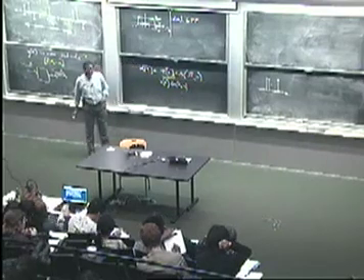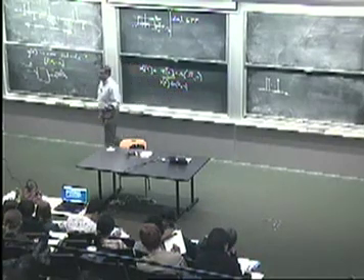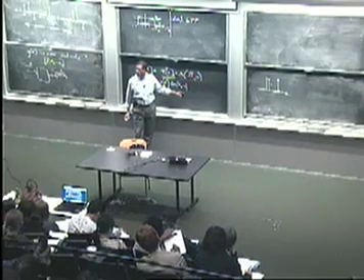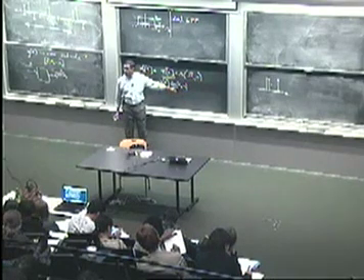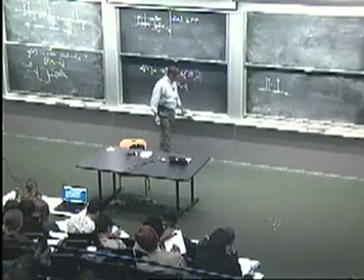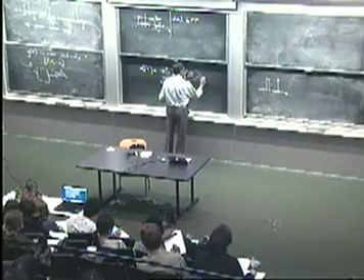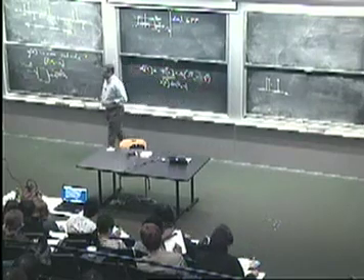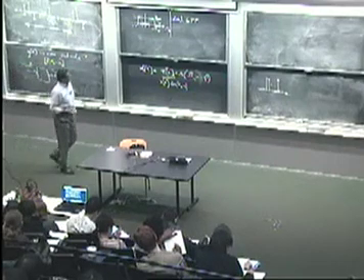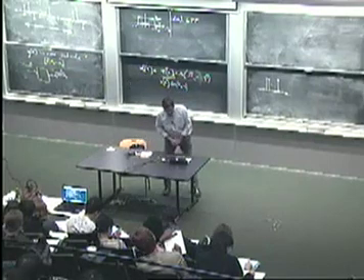But there's a bit of a problem here, which is that even if you've been told what carrier frequency your sender is going to use, you might not know exactly what phase. It's typically the case that you don't know what the phase is on this cosine. So you know omega c, but you don't know exactly the phase, which means that your local oscillator or your local carrier multiplication here will end up having some offset relative to the carrier used at the transmitting end. Okay? And so the question is, if we track this through, what happens through the demodulation process?